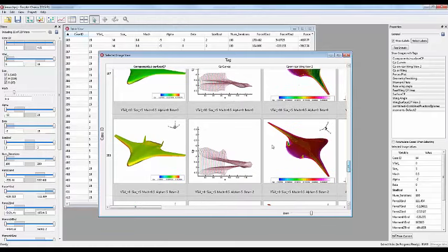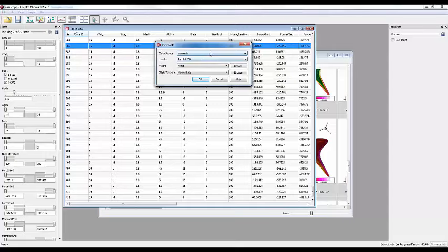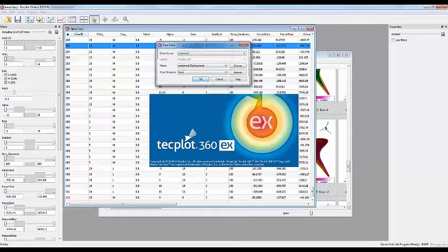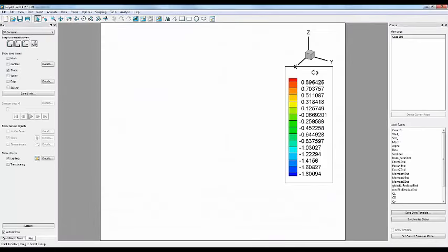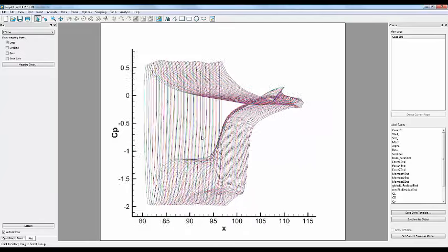All of these data that I show you here were created in the same way with a right-click. We did a view data effectively where we looked at, say, the combined data with, let's say, the combined 3D view or the CP extract and no style. And if I do this, basically it's going to do the extraction of CP, and I believe if I go into align mode, you can see this a little better by looking at X versus CP. And there you go. So there's the CP curves. So it does an extraction.